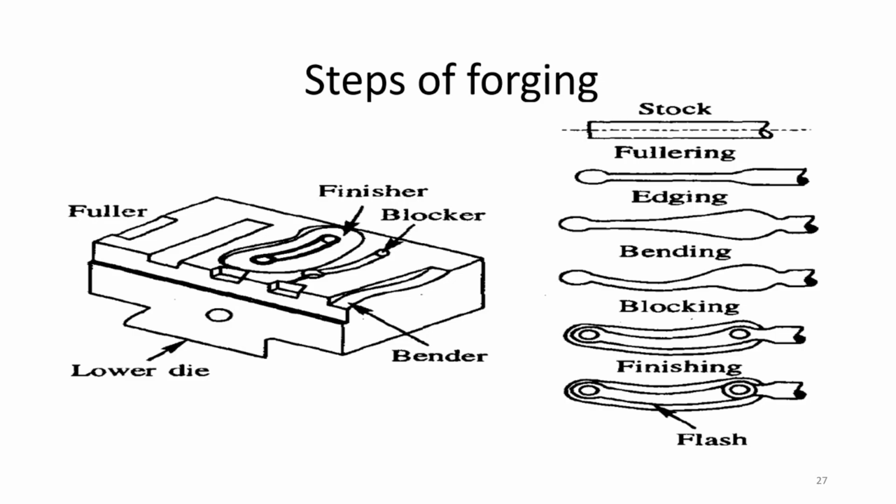No, austenite is austenite. You will be getting retained austenite here. You can get simple austenite as well by altering the alloying elements in your material. That will be completely different compared to what you are trying to achieve here. Here we are changing the cooling rate parameters, and with that you get martensite and retained austenite. This retained austenite will be low, up to 5% or so. This will also depend on your alloying elements.